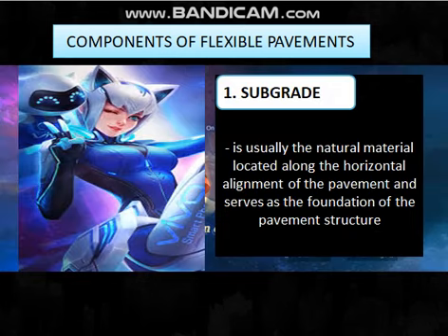Subgrade is usually the natural material located along the horizontal alignment of the pavement and serves as the foundation of the pavement structure. It is necessary, guys, to treat the subgrade material to achieve certain strength properties required for the type of pavement being constructed.